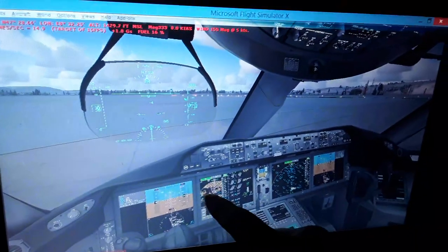So you can see also the airports, the names of the airports. We have the navigation aids. In the navigation display, we have the VOR stations, the ADFs, the NDBs, and the waypoints, which are horizontal and vertical navigation fixes the aircraft has to traverse as it flies. So it will follow the purple line here. You can see the magenta line of the flight plan, the flight management computer we just created. I will show you the process.